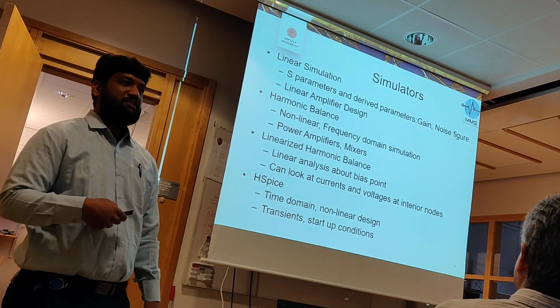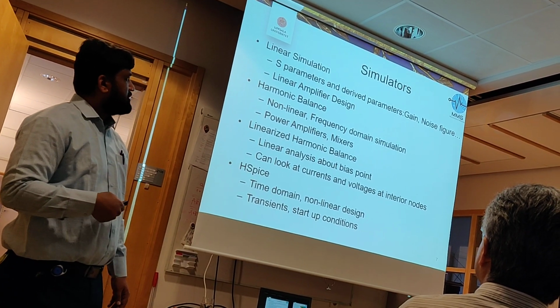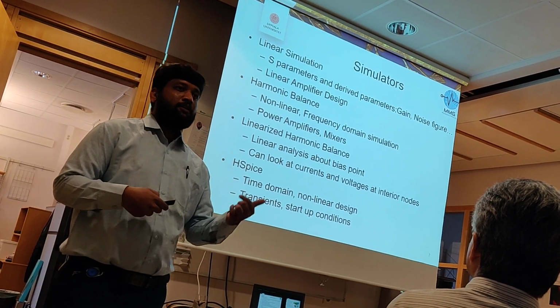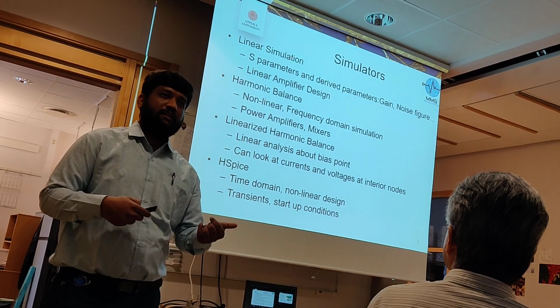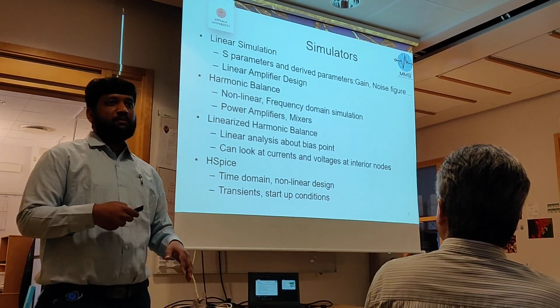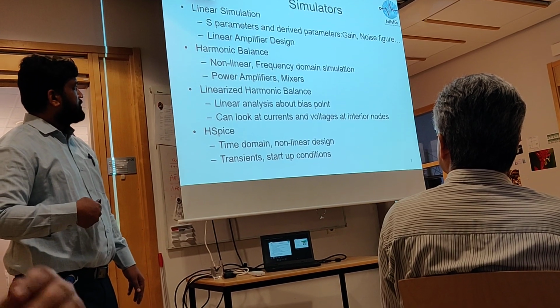So that kind of linear analysis can be made with linear simulation. S-parameter analysis is like small signal analysis for circuits. And harmonic balance means we can handle the non-linearity of circuits, where we can understand the harmonic effects and intermodulation, dynamic range of the power, everything you can measure, and special devices like power amplifier and mixer.